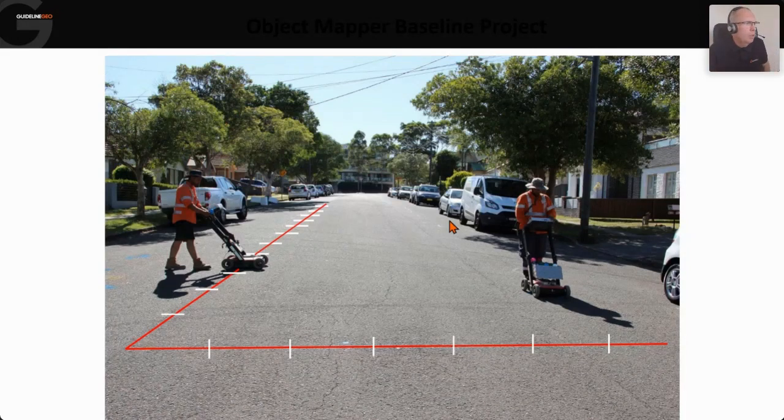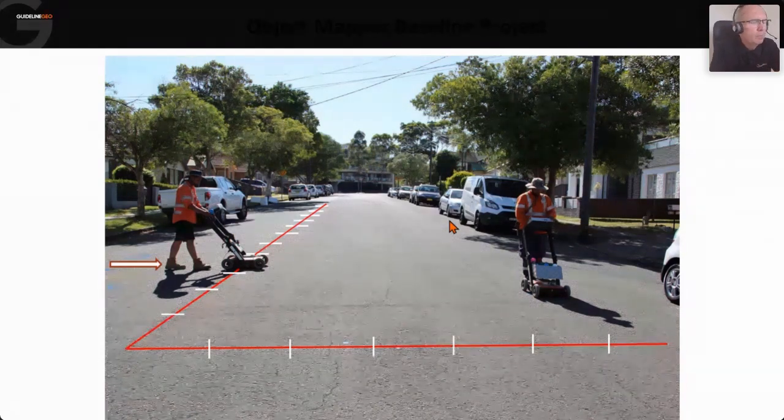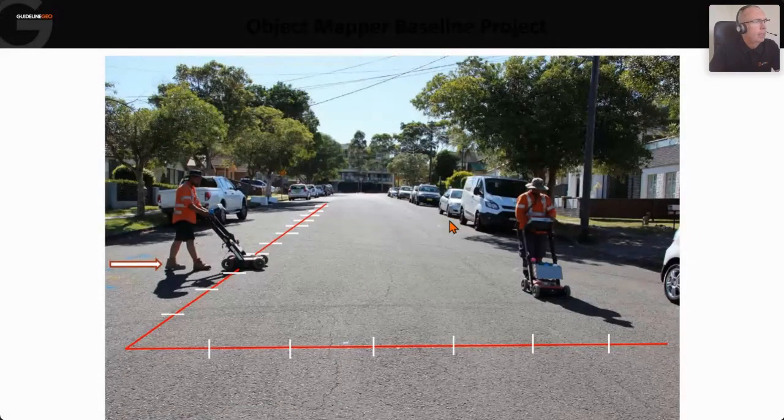But the idea is we're going to start with the radar, move it across the street, and come to the baseline. We will pause for a second with the radar. We enter the information into the GPR of the position along the baseline and which direction we're moving in. Then we create a baseline crossing in the data set itself, and we continue to move across in that direction. We'll continue up the street along the baseline progressively as we go.